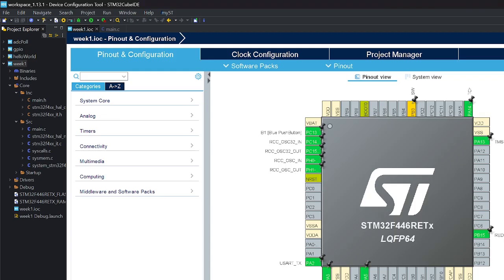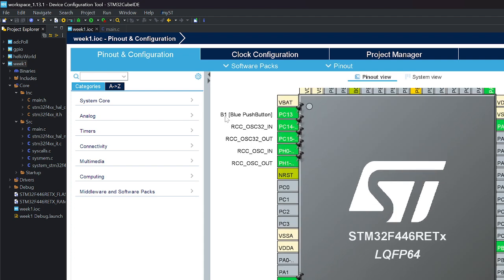If we go look over at the IDE, it says B1 there in brackets. That's just for more information from the documentation, but it was called B1. I called my PB15 red LED last time. Whatever you call it, it's going to make a name, a port and a pin. So if I have red LED, then on PB14 green LED, and on PB13 maybe blue LED, it's going to make the port all port B, GPIOB, and the pins 15, 14, and 13.